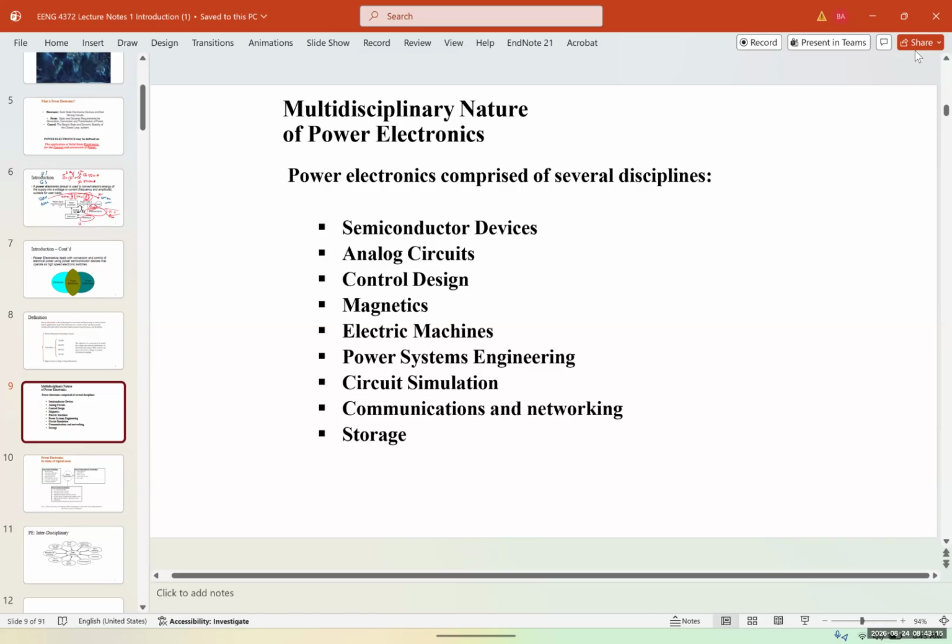Newer EVs use AC motors, but the thing is, the battery is DC, so you need a power electronic unit or an inverter to convert that DC battery voltage to AC to run the motor. The reason that they use AC, asynchronous motors or synchronous, is because it's very efficient and it doesn't require maintenance.